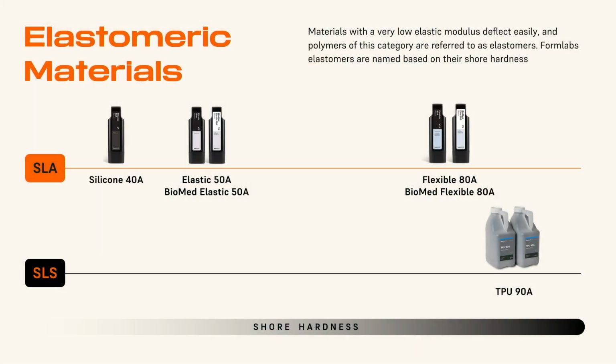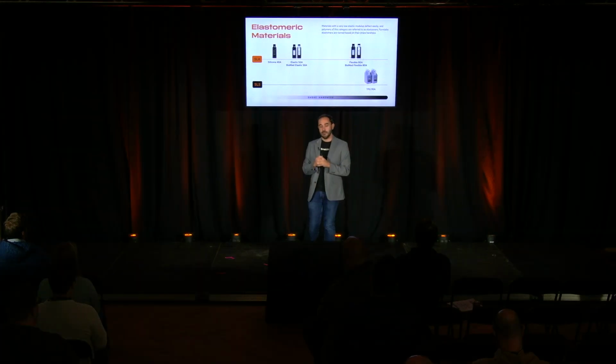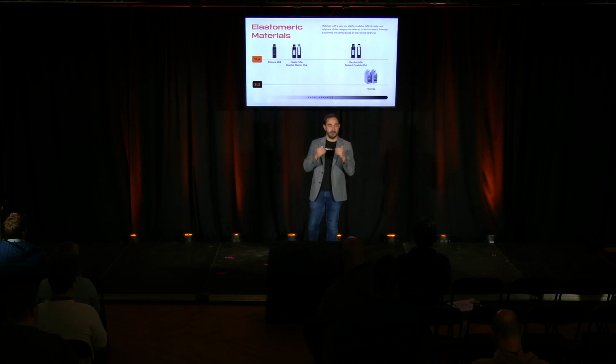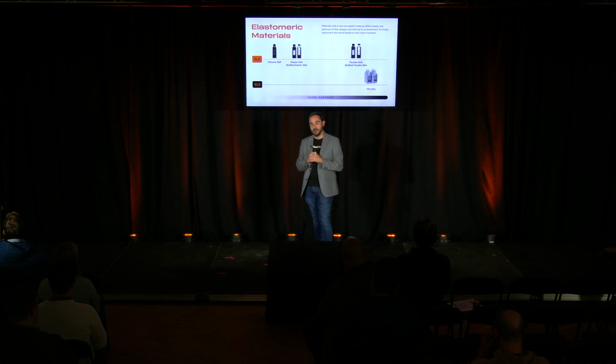So another group that I have is now going the other direction again. Some materials have a really low elastic modulus. In fact, their elastic modulus is so low that elastic modulus doesn't become a really useful criterion anymore. It takes so little force to elongate these materials that we want a different metric to evaluate them and put them next to each other. So we use a property called hardness. Hardness is just localized deformation in response to stress. So we're still doing a stress to deformation relationship, but it's localized in the material.